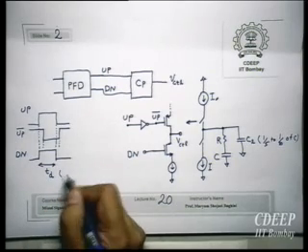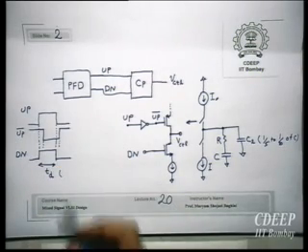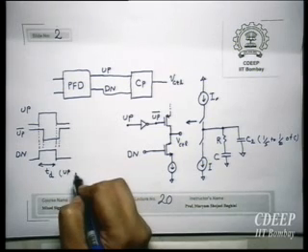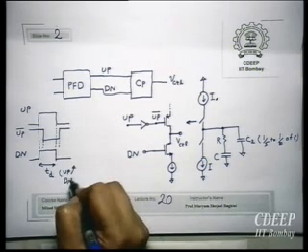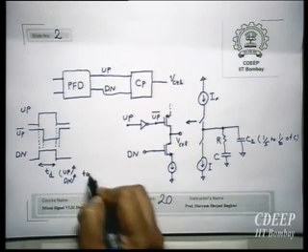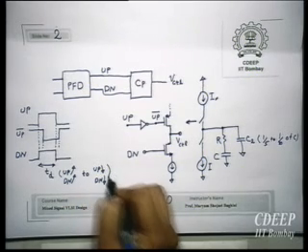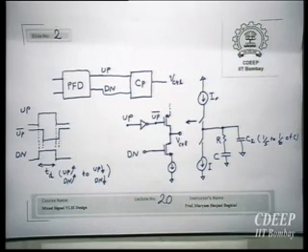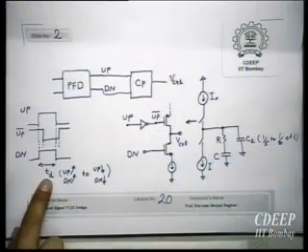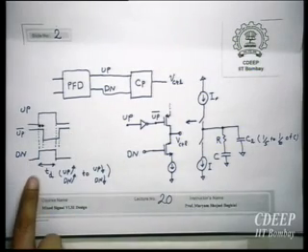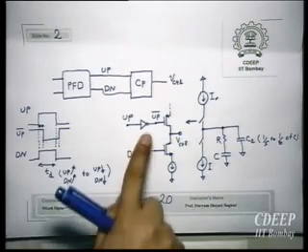This was the delay of the pulse frequency detector, from when up goes high, down goes high, till the time both go low. And this happens because when these two are high, it goes to an AND gate, then it goes to reset, and reset has its own delay, the AND gate has its own delay, so this will create that delay. Now, the delay of one inverter will be here. Therefore, practically we will have this type of waveform on up bar and down.